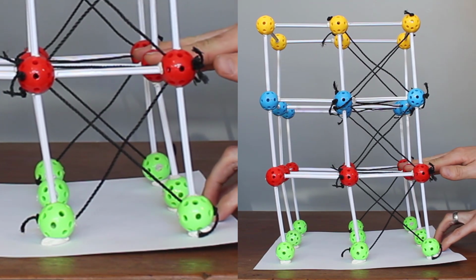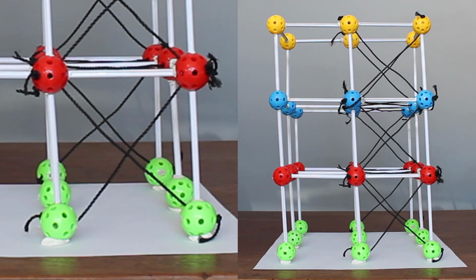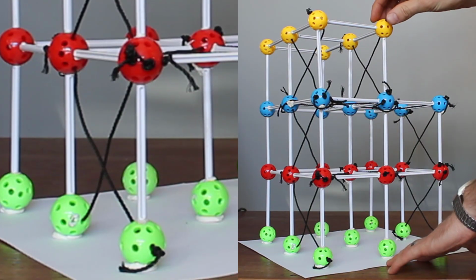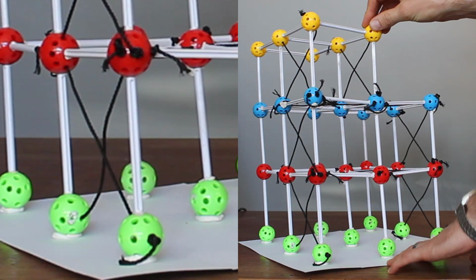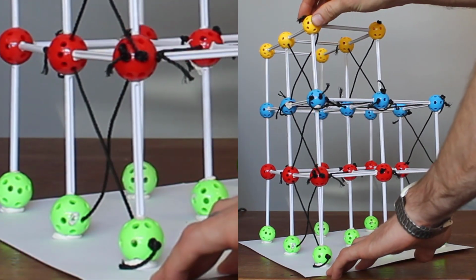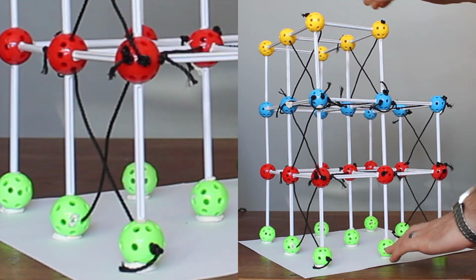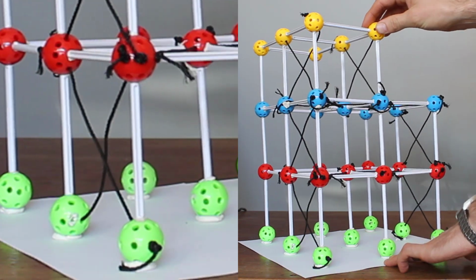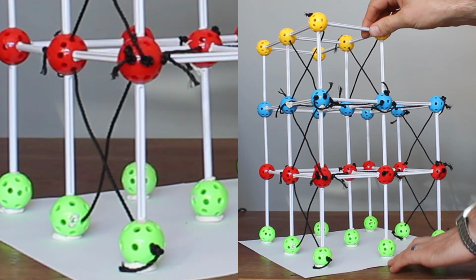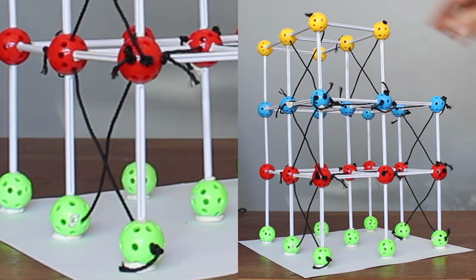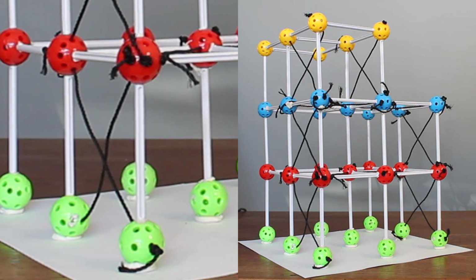You can also see how when we load different parts of the structure, then different brace bays carry the load. Here you can see the same thing just from a different angle, loading the middle bay, then the load gets transferred to the braced floor bracing and across, loading the side bays, etc. And once again you can see how the braced bay, which we've zoomed in on, when it's loaded, that brace goes into tension.